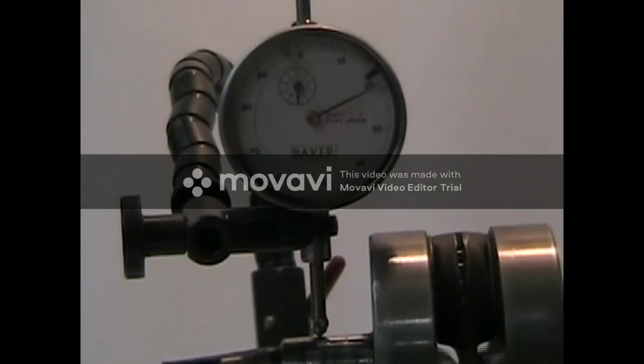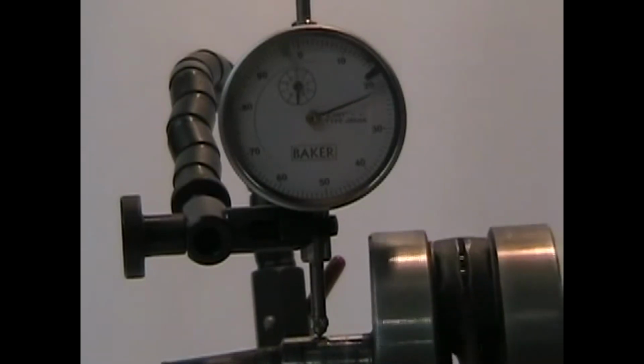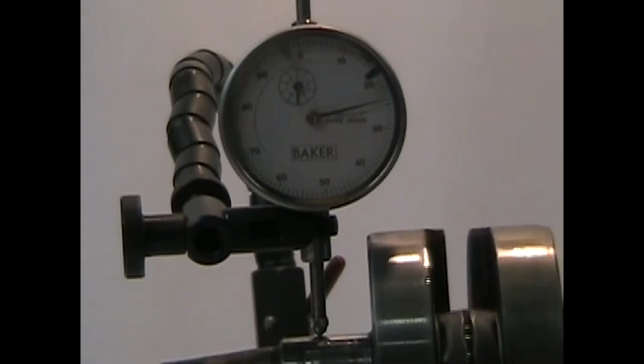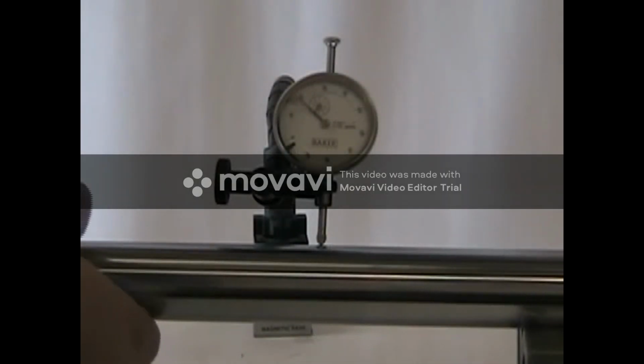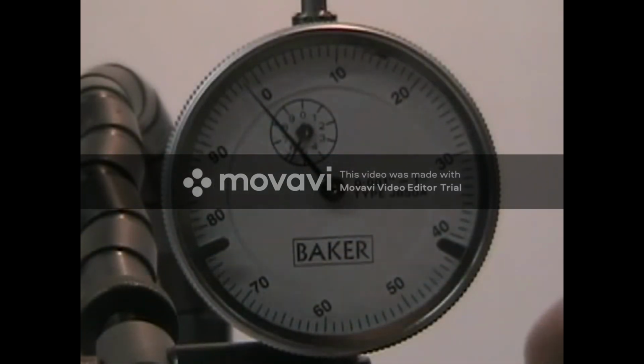Lock the indicator into place and carefully rotate the part while you observe the dial readings. Read the dial face straight on so as not to read the wrong measurement. If the pointer does not move while the part is being rotated, the part has no runout or surface distortion. If it moves, there is runout or surface distortion.